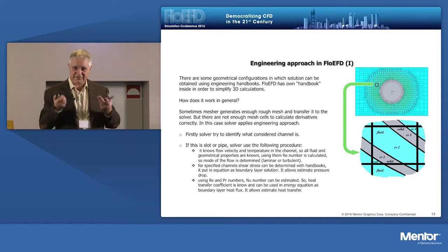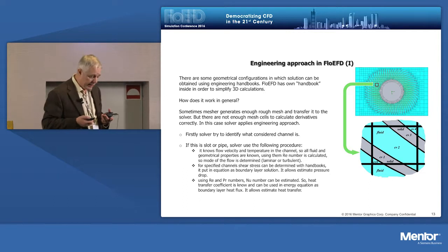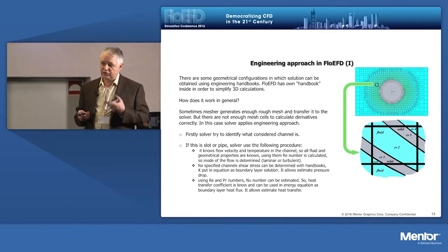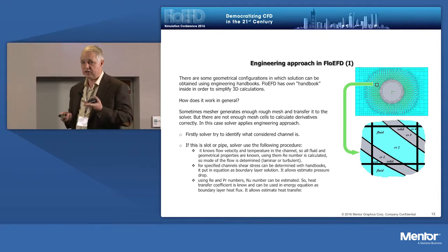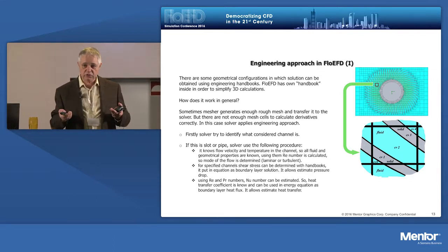So these cells really understand where they are, what is the Reynolds number, what is the thickness of the boundary layer, are we inside or outside some analytical solutions, and manage the situation. This is why I like this name. And this allows us to save the resources. This allows us to use rectangular grids, which are very easy to make fully automatic grid generation.